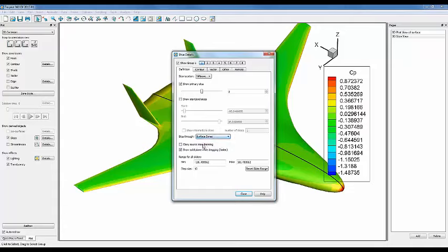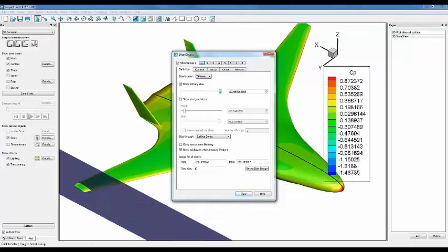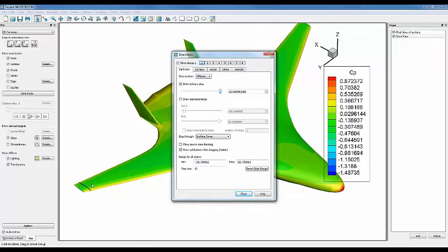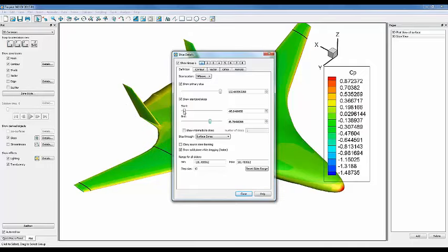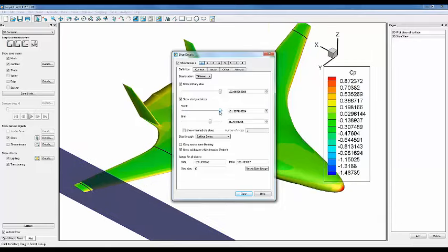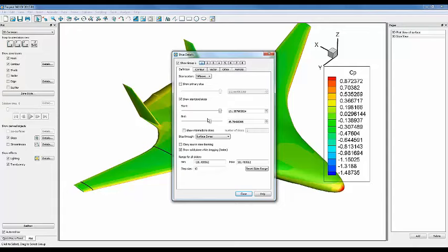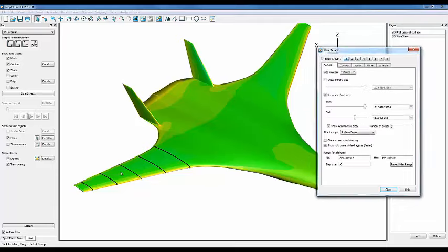Now we want a surface zone. We could move that to, say, about 10% of wingspan, or 85% of wingspan, depending on your point of view. And we can also add a start and end slice, and then move the start and end slice. So perhaps let's put the end slice there and the start slice over here. I'm going to turn off the primary slice. It's unnecessary. I can add intermediate slices, perhaps 3 of them. So now we have about 5 slices on the wing. Move this out of the way for a moment.